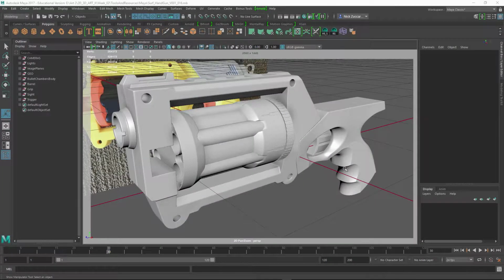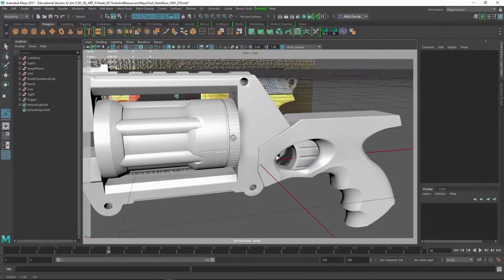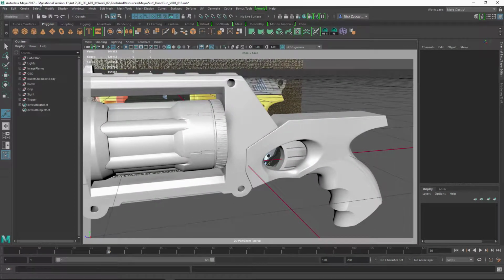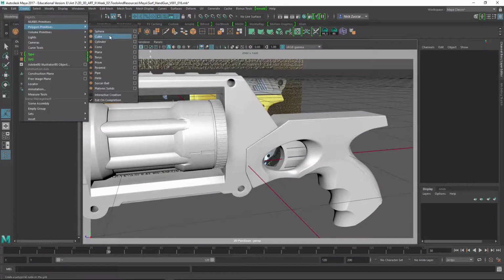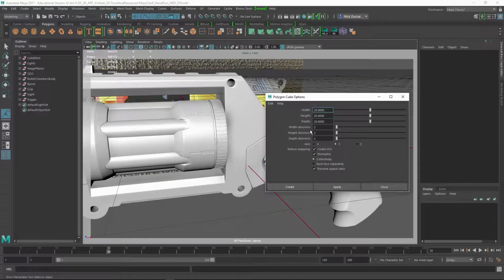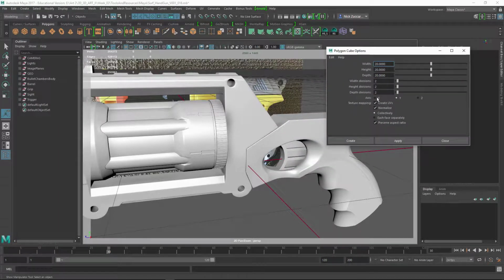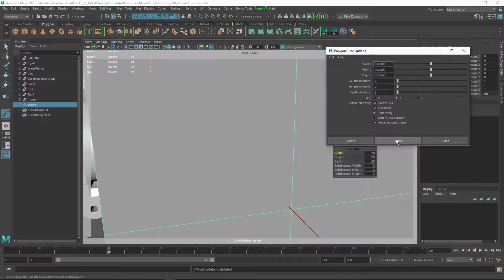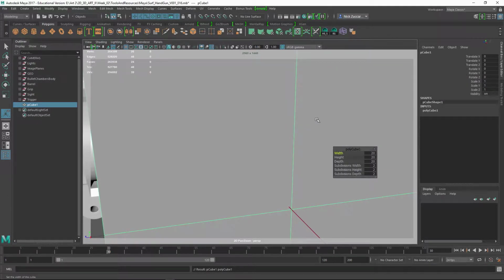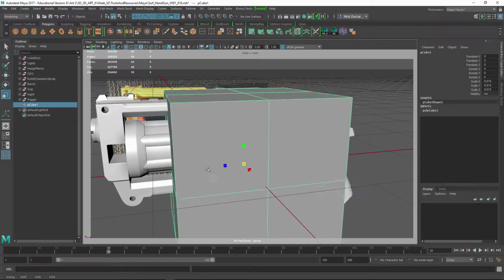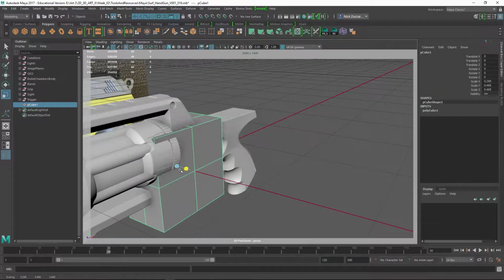Okay, inside of Maya, we're going to continue on with that shape that we've been working on for a while. We're going to go ahead and just go up to create and do polygon primitives. We'll do a cube. And I don't think the creation options matter all that much. I do have a division of 2, 2, and 2, so with these settings you can see I'm going to get a cube kind of like this, and I'm just going to quickly scale it down, kind of roughly get it to about the right size here.